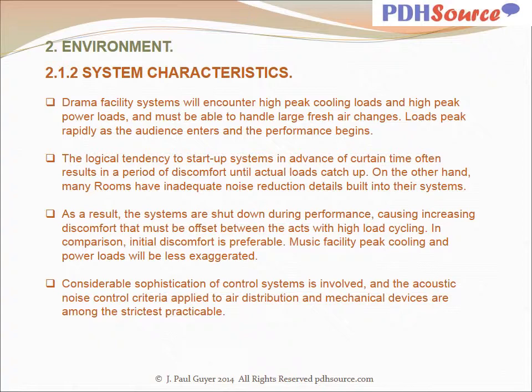With regard to system characteristics, drama facility systems will encounter high peak cooling loads and high peak power loads and must be able to handle large fresh air changes. Loads peak rapidly as the audience enters and the performance begins. The logical tendency to start up systems in advance of curtain time often results in a period of discomfort until actual loads catch up. On the other hand, many rooms have inadequate noise reduction details built into their systems. As a result, the systems are shut down during performance, causing increasing discomfort that must be offset between acts with high load cycling. In comparison, initial discomfort is preferable.